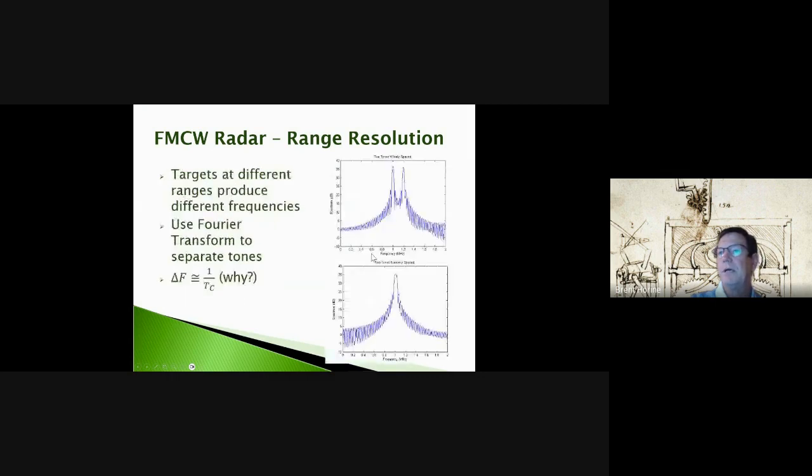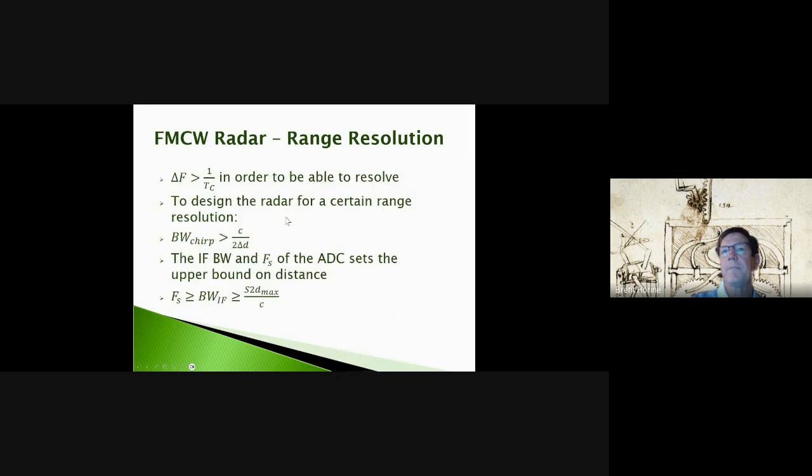We would do a peak search through this to try to resolve these things. So here there's clearly an inflection of the slope. It goes from positive to negative, and then positive to negative. So we can determine that's a peak and that's a peak. We do some threshold there as far as an algorithm.